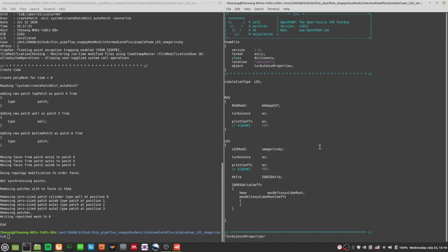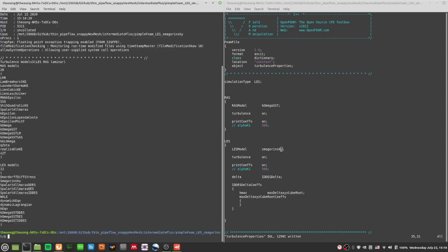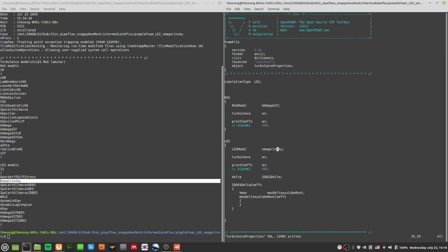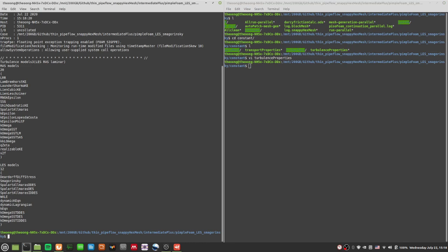Let's see what else we should put. Let's check first whether I spelled it right. Okay, list turbulence models. Smagorinsky has to be spelled with a capital S, so let's put a capital S in there. Everything else I won't change at first. Let's see what errors we run into as we go, and we'll start from there.